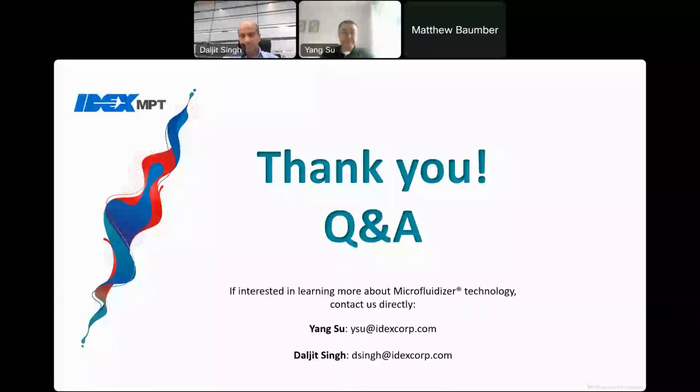Which parameters do you need to control to obtain a uniform particle size distribution? And how can you assess the uniformity? So I would say the uniform particle size is somewhat inherent from the technology and the machine design. Like I said, our constant pressure intensifier pump with the fixed geometry interaction chamber will achieve constant process pressure, hence will give you uniform particle size in processing.